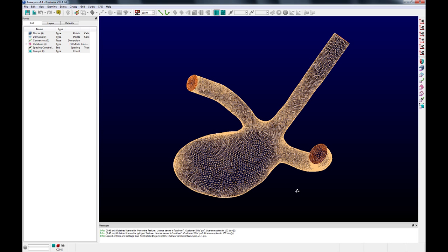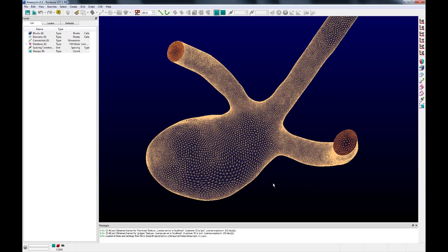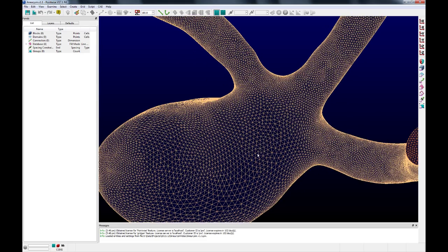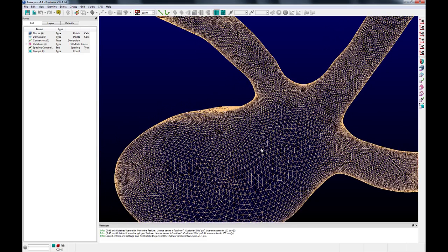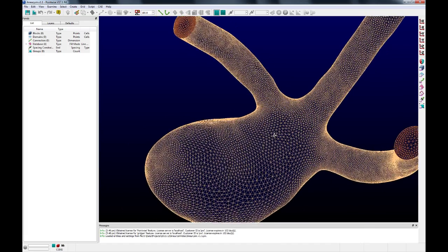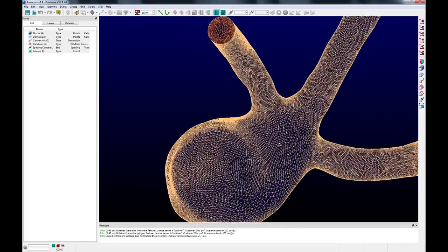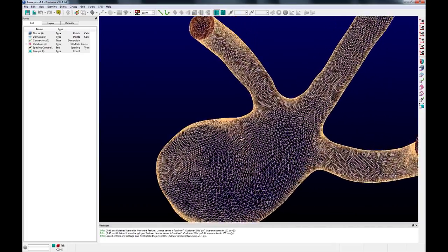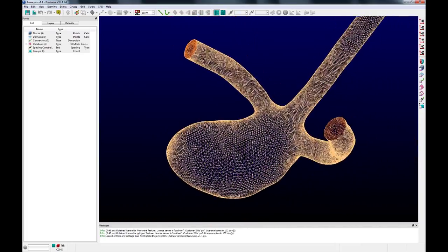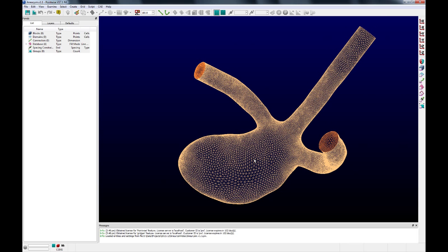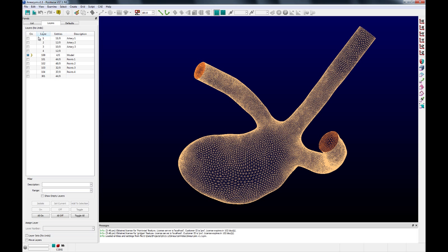So one thing to note whenever you import an STL format is that each of these points here on the triangulated surface mesh are pickable points in Pointwise. So for a good high-quality, high-density surface mesh like this particular STL, there are actually a number of points that we can snap to whenever we're sketching our initial wireframe. However, to make things a little easier, I actually found that applying database points to the surface of the mesh made it a lot easier to sketch out these curves.